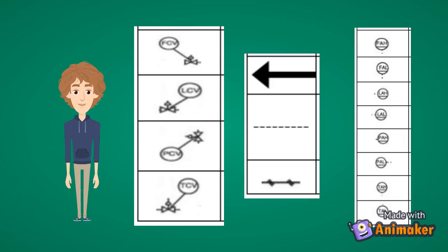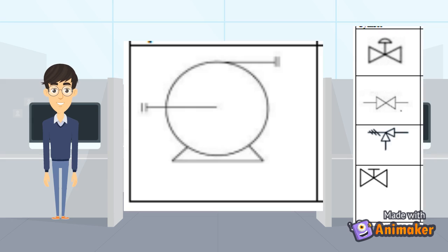Next, these are the final control element, piping, and alarms that are found in the P&ID. Flow control valve, flow alarm high and process flow line are the examples of it. Finally, these are the valve and pump that are found in our P&ID. There is only one centrifugal pump and 4 types of valve present in this P&ID.